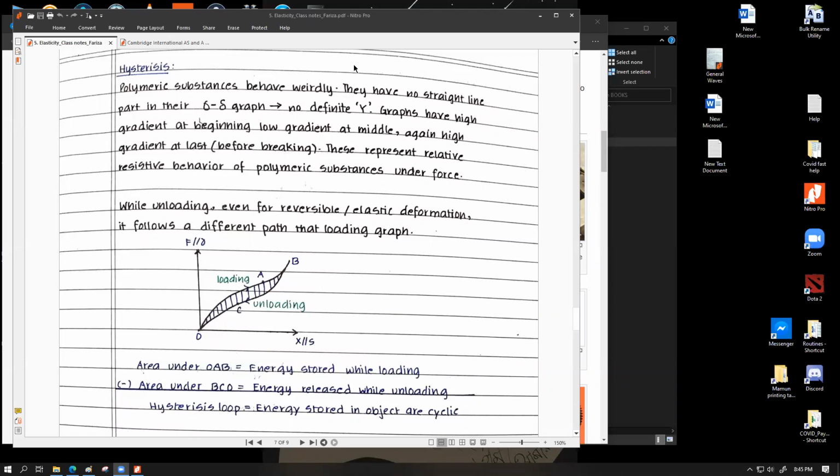This is equally applicable for everything that is made up with rubber or some compound of rubber, some other compound. For example, if you think for tires of cars, try to think about it. A tire is usually a round shape, but the location where it actually contacts with the ground, that part is always somewhat squashed because at least about 1/4 of the car's weight applies to that tire, right? So which means every single time a tire rotates 1 revolution, every single part of that tire underwent 1 full cycle of this loading and unloading.